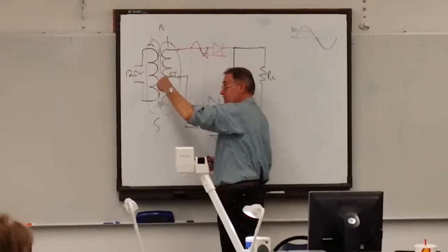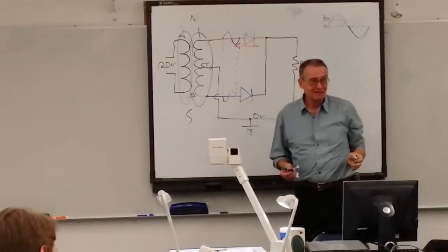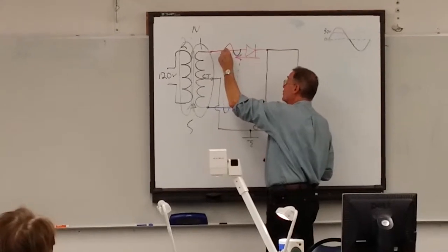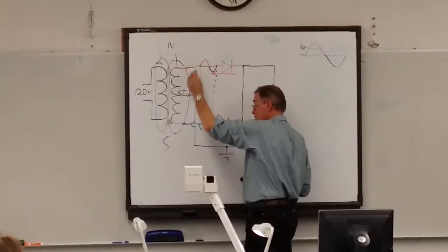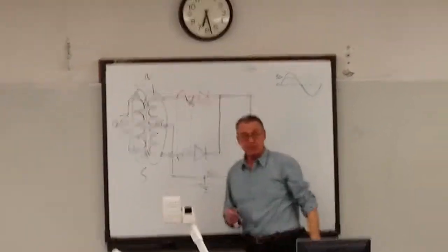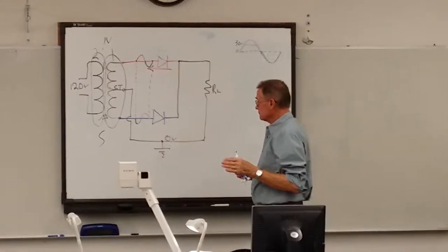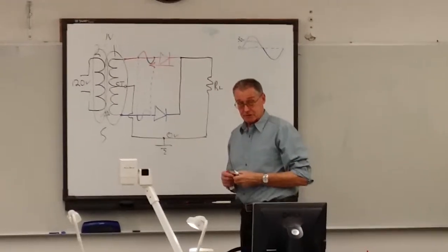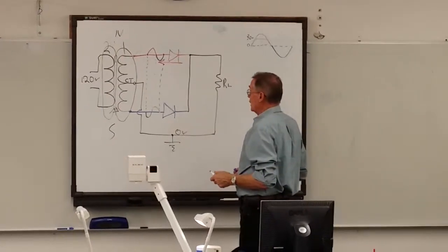If this is a magnetic field, there's a north and south pole, we know they're opposite polarities. So that's why, no matter what, anytime you have a positive on the top side of a coil, the bottom side will be negative. The only way around that is to ground it like we did on the half wave, and that makes it 0, but you're not going to use a center tap there.